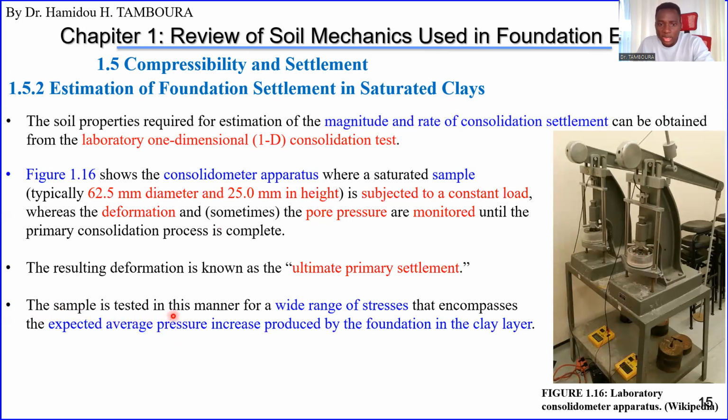So the sample is tested for a wide range of stress, and you choose a stress according to the expected average pressure increase your foundation will experience during its life on the construction site. What is the average pressure increase produced by the foundation in the clay layer?